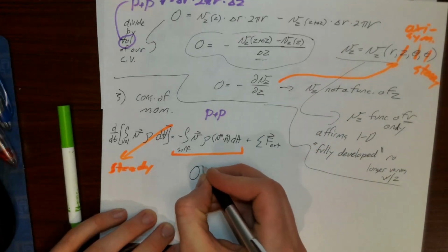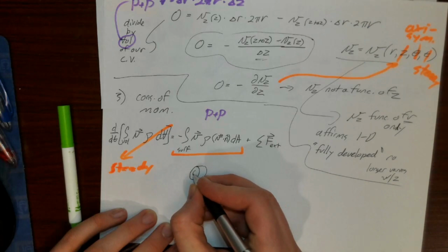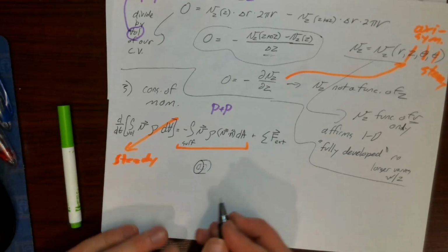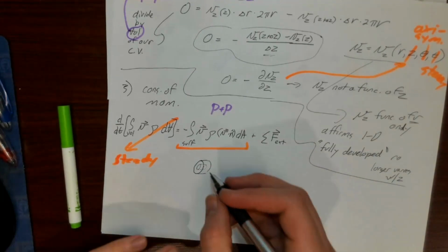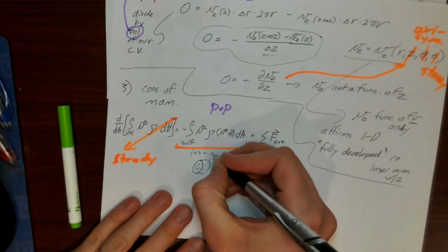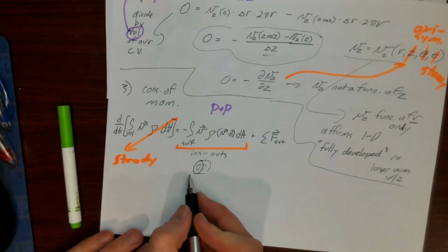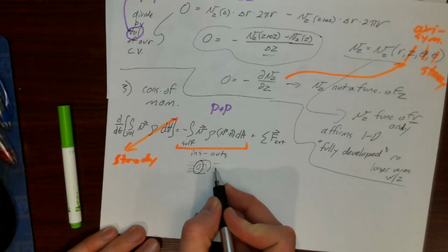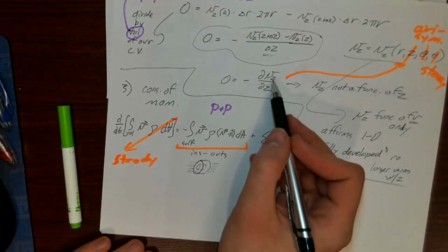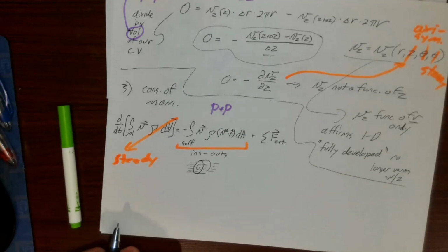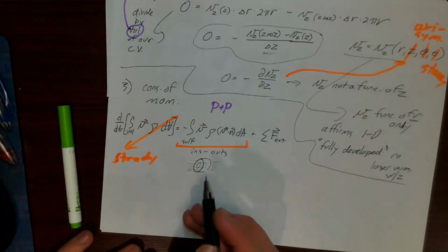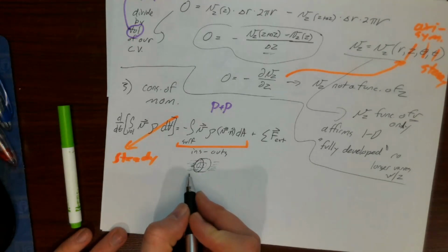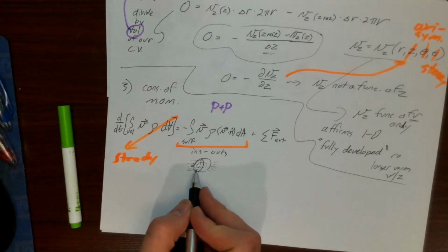Right, so let's sketch my control volume right here. This is essentially my ins minus outs. What can I say about the momentum entering through this face as compared to the momentum exiting through this face if my z velocity doesn't vary with z? Well, I might have some momentum in any direction entering through this face.